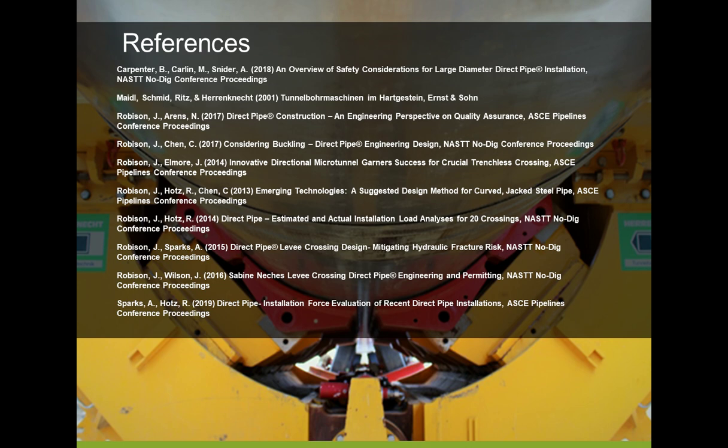And then part of that is that you might have a smaller diameter pipe and you're pushing a larger diameter machine because you want the capacity of the big machine. For instance, one of the projects we did was a 42-inch pipe, but we really wanted to push a 48-inch machine. By the time you skin the 48-inch machine up to get the cutting wheel on it, you've got a 53 or 54-inch diameter hole that you're then pushing a 42-inch pipe through. So much larger in general, I think, is probably a fair statement there.